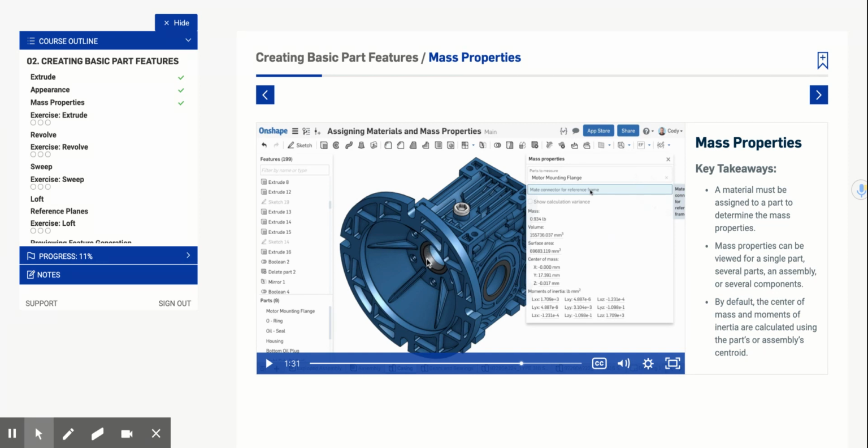So if you designed the cylinder and then you designed the opening on this blue plate, you want to make sure that the dimensions are the same, but when you have a mate, like one thing goes into another, then you don't want them to be exactly the same dimension because they can't exist in the same location.